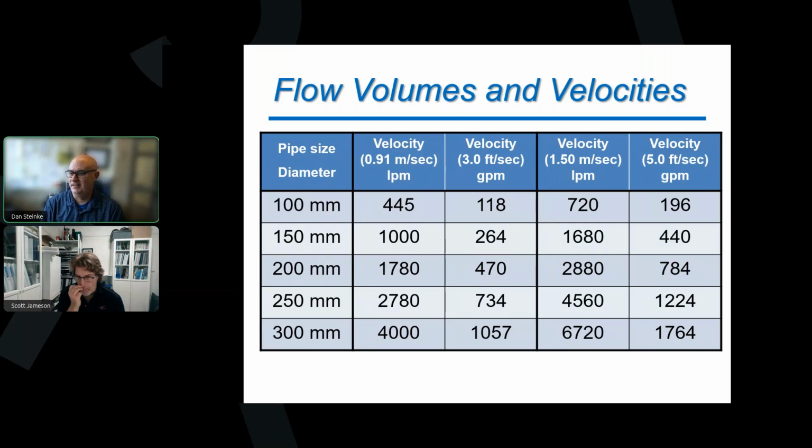Arthur asks, can we start with hydrant 1 to make sure the incoming water is clean? I believe this is in relation to example 3 again. Yep, not a problem. Perfect way to do it. Excellent. That's usually the first thing we are doing. It's nice to do a nice short little run and make sure that everything's working the way you think it's going to work. Perfect, good way to do it.